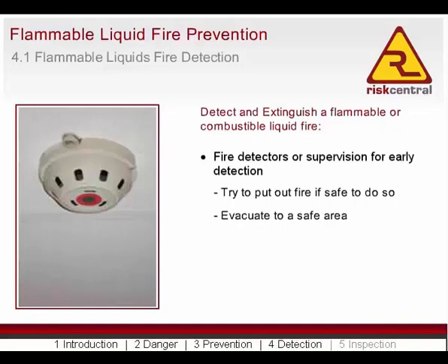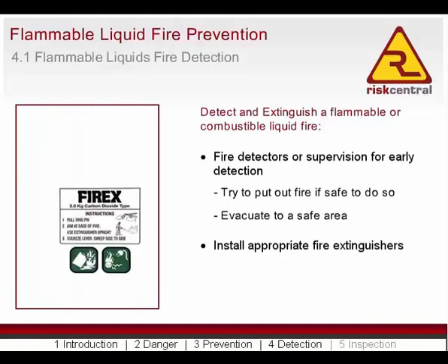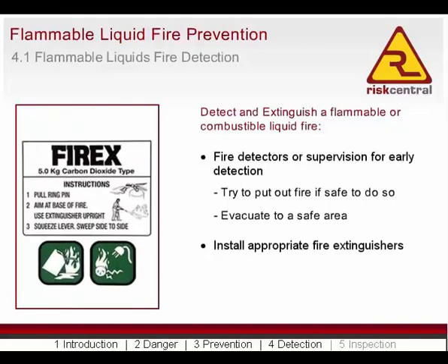In most situations, the right type of fire extinguisher will be a great help, but only some types of fire extinguisher are recommended for use on flammable liquid fires. If the wrong type of fire extinguisher is used, or if an extinguisher is not used properly, you could help spread the fire or you could hurt yourself. We recommend you complete a fire extinguisher training course, especially if you are handling flammable liquids regularly. Appropriate types and sizes of fire extinguishers should be located near flammable and combustible liquid storage areas and process areas, as well as throughout your site.